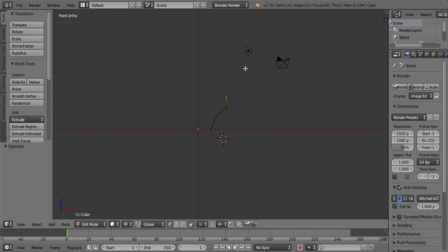I'm just going to press Ctrl Z to revert back to one vertex, and I press E for extrude. Now when I move, a single vertex becomes a line as well, but now I'm in grab mode, so I press the Z direction and I hold down Ctrl and I'm moving 5 steps upwards, something like that. I left click before releasing Ctrl, and now we have a line with length of 5.